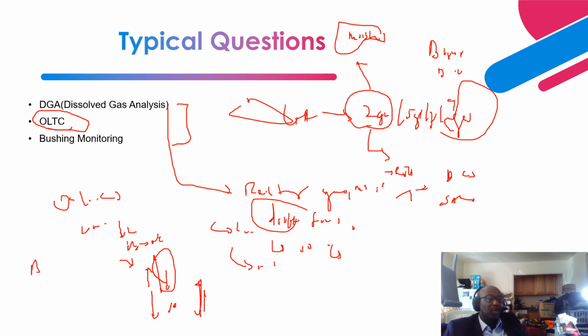It works based on the bandwidth set for the voltage regulator. You also have other monitoring in place: your motor current, the motor torque, contacts, and wear. These are typical measurements that the OLTC spits out on a real-time basis.